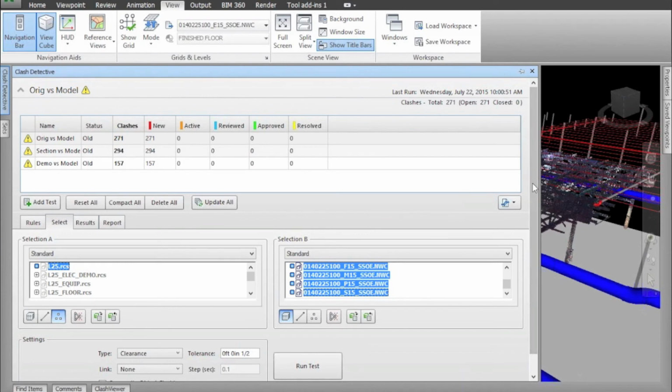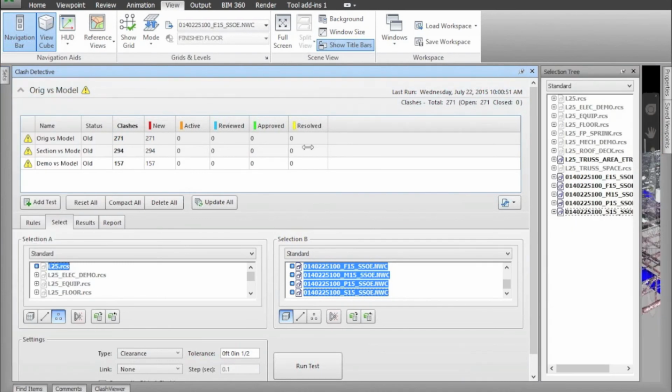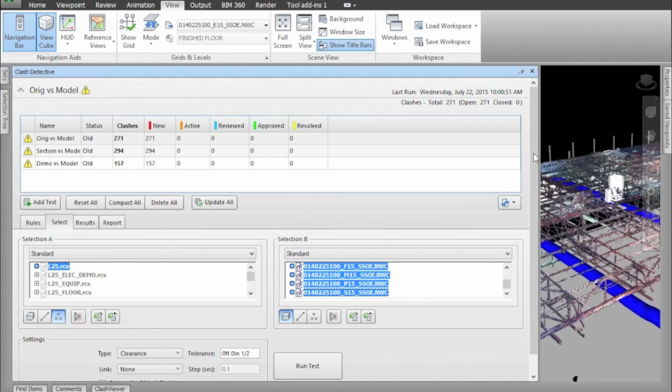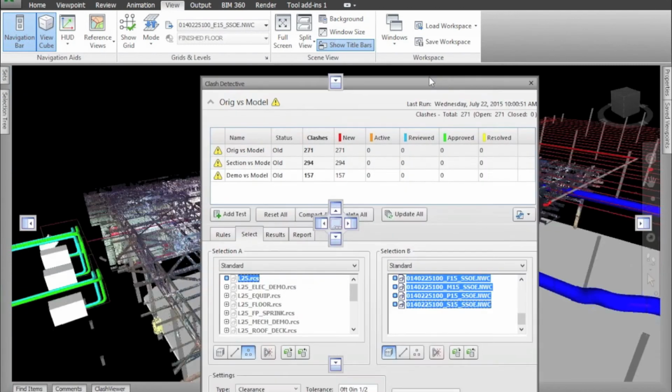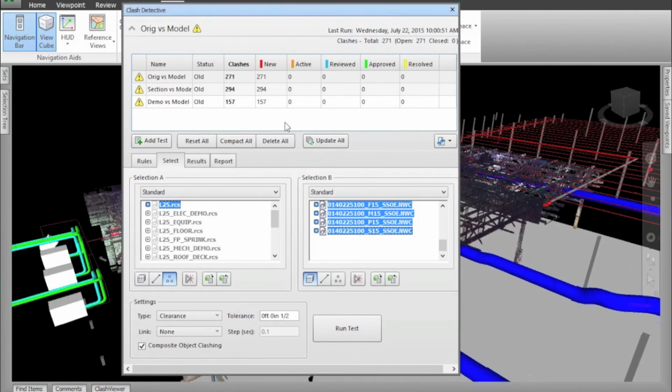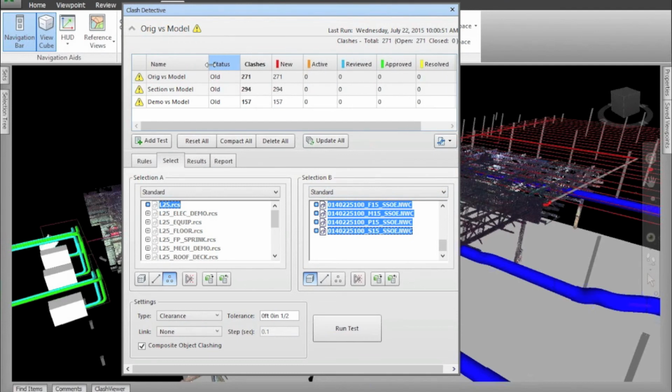One thing I want to mention is clash detection here. This is another proof of why we do this, because it might sound like we're making a lot of work out of something to not get a lot of return. But once again, we're getting plans, and we don't have to model stuff, which takes a lot of time. Also, when you look at clash detection, you end up chasing your tail looking at a set of demo drawings and finding what is really not to be demoed or what is going to be demoed and saying, okay, that's actually not a clash, we can keep our ductwork there.